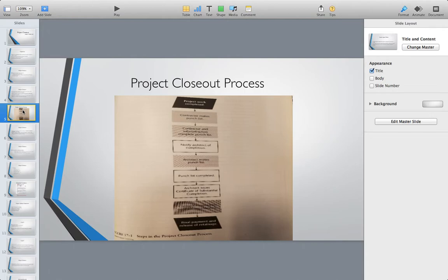Once the punch list has been officially completed and signed off by the architect engineer, saying that yes, we verify that everything here has been completed, then the architect issues a certificate of substantial completion, and the contractor completes the contract requirements. Then final payment and the release of retainage occur, of all the monies that have constantly been shown on the progress payments. The retainage amounts are then released. So that's figure 17-1 on page 443 of your textbook.